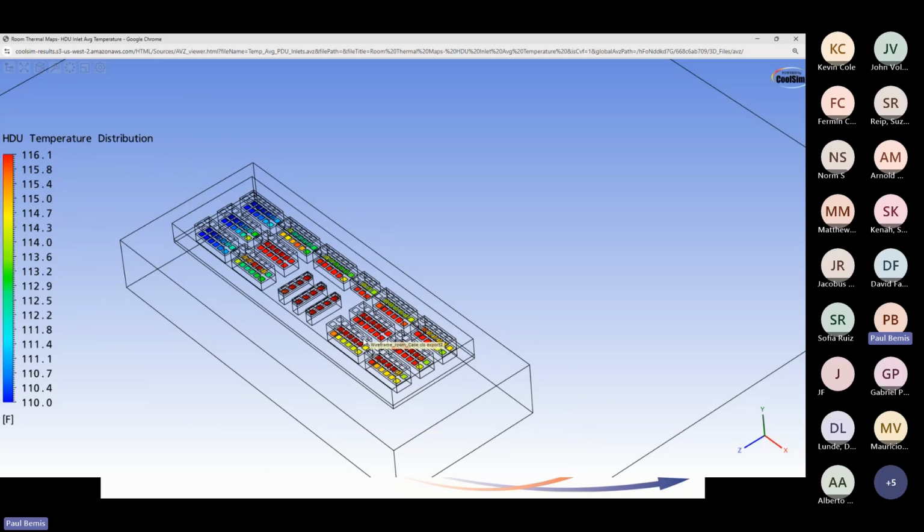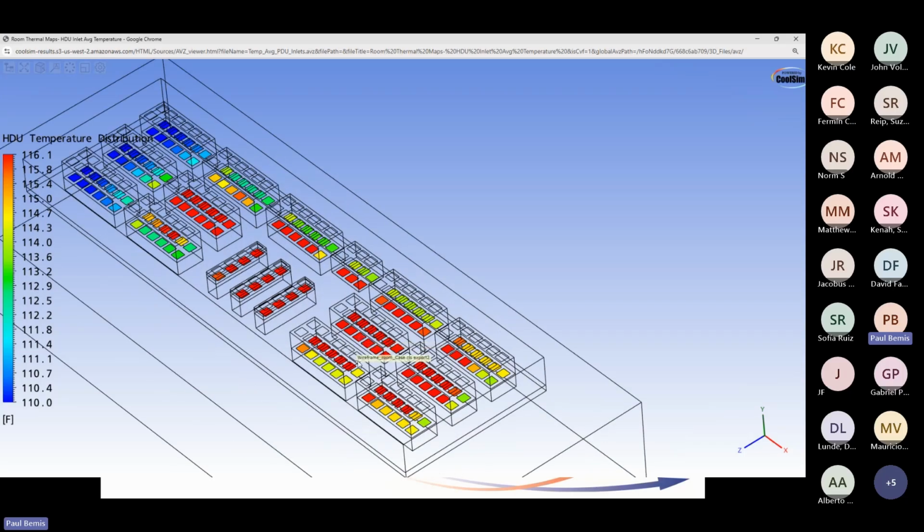However, it's not always fine, believe me, because we do a lot of these and those things get really high. If you start to get up into the 140-degree range, the compressors will actually trip and you'll have a high pressure condition and the chiller will shut down. And it can occur. I've seen it occur. It depends on how much density there is. Depends how many chillers there are. Depends on, as you'll see in a moment, is there auxiliary generators running, for example, that are adjacent to this system.